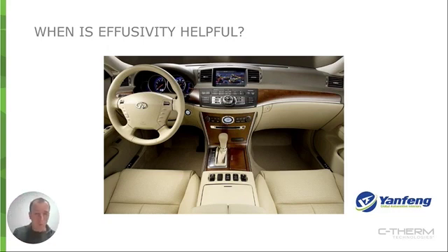But the problem, of course, is that with wood and leather as natural products, they have consistency issues. So you have a higher manufacturing cost working with them. They're also heavier, so they have a negative weight ratio from a fuel economy perspective. So we would prefer to incorporate composites here, synthetics that perhaps look like the real thing, but are lighter, more durable, more consistent, and cheaper.